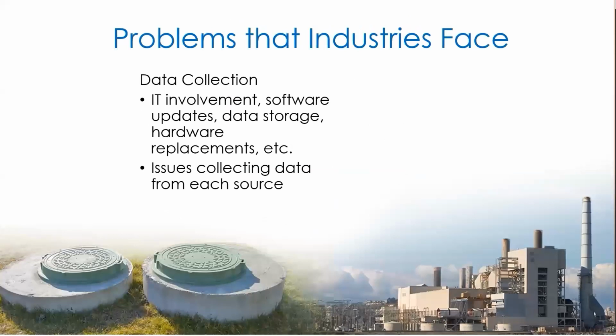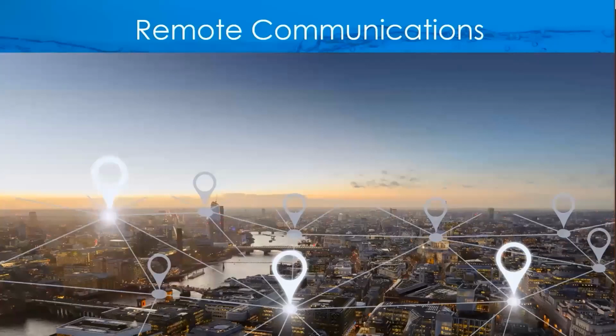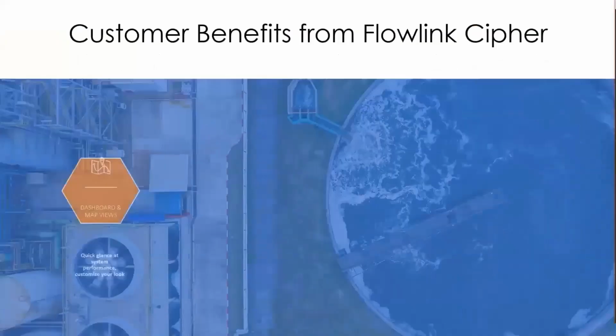Some of the problems that face the industry is the data collection, and I mentioned downloading that data, which involves software. You need a place to store the data. The IT departments anymore don't like to get involved with the data storage and setting things up on your computer. So that's where using remote communications really helps free them up and you. By using a cell phone modem on your instruments, you can push the data out to the cloud.